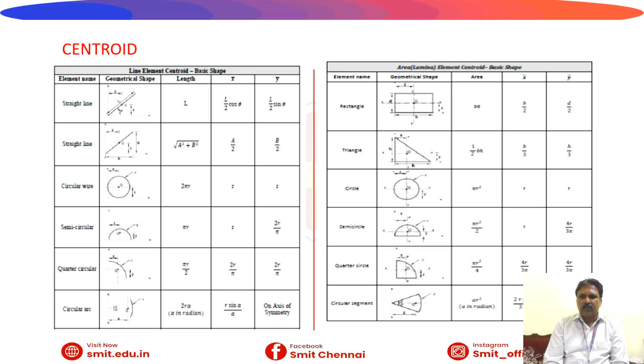Then the circle has area pi r square, with x bar equal to r and y bar equal to r. For the semicircle, the area is pi r square by 2, x bar is r, and y bar is 4r by 3 pi. The quarter circle has area pi r square by 4, and x bar is 4r by 3 pi, and y bar is also 4r by 3 pi. These are the important formulas. The students must know that before solving the problem, these formulas are very, very important.